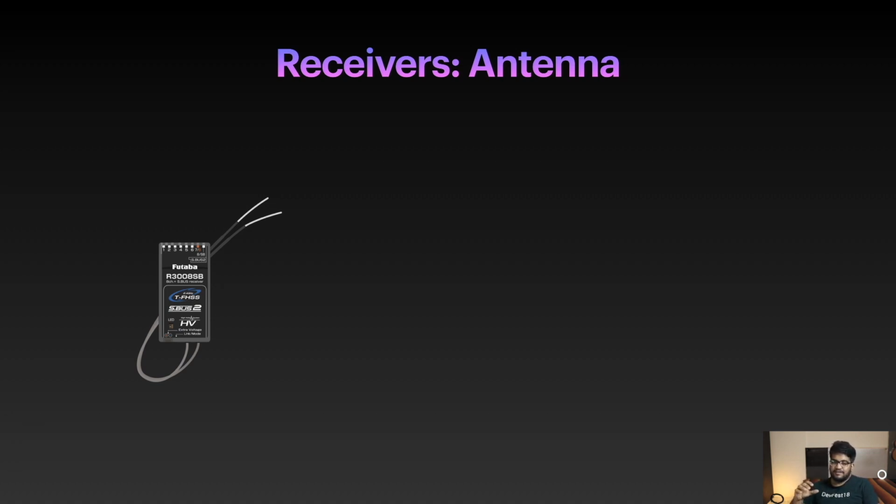There is a concept called impedance matching that is used everywhere in electronics. If the antenna is not matched for that frequency, and the transmitter is sending signal out at some power, it can burn the transmitter, because there is no way for the signal to go out. The transmitter wants the signal to go out via an antenna, but if the antenna is crappy, it will burn the transmitter. So the design of the antenna is very crucial there.